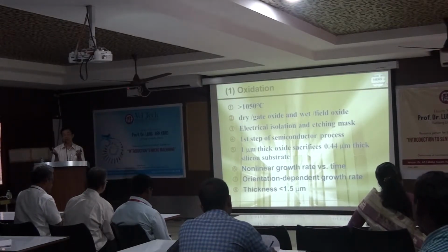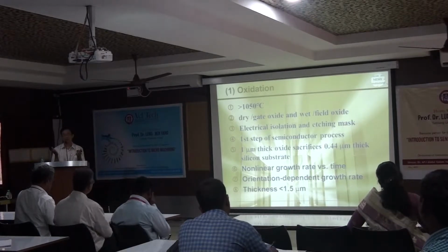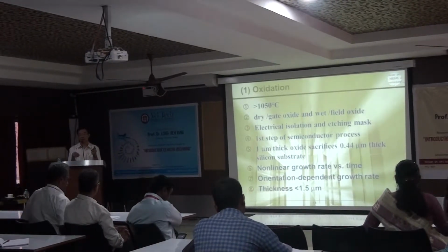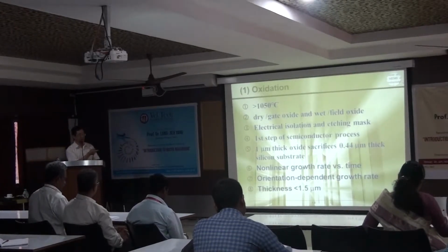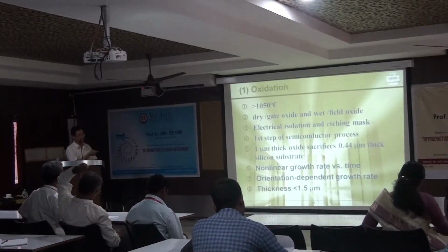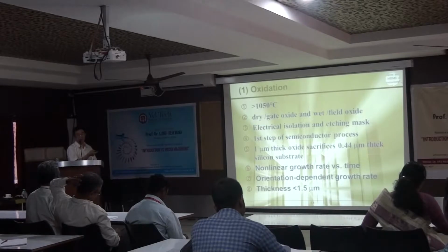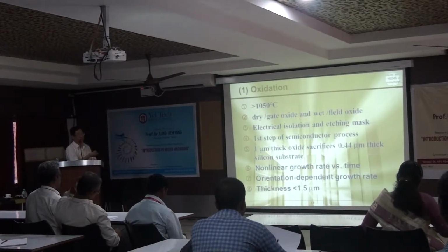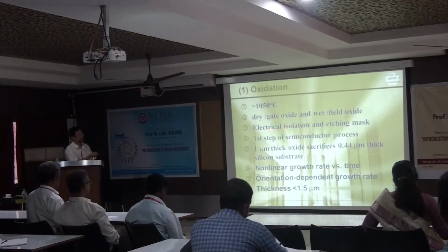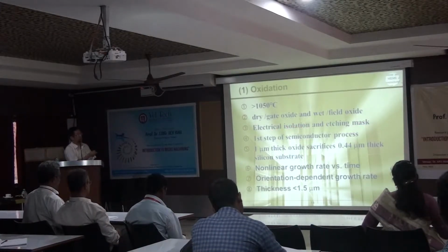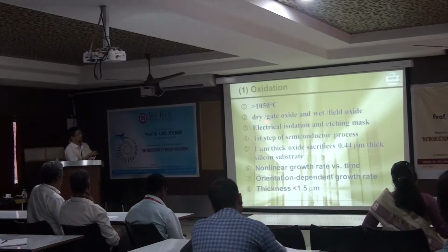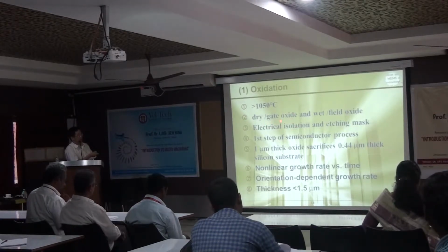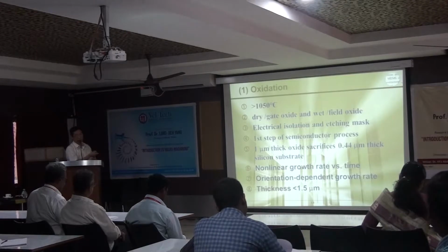Acid, even strong acid, we use the glass container to hold it. So it means that it can prevent the attack of the acid, strong acid. So it's good as an etch mask. So two functions for the oxide: electrical isolation and the etch mask. And also we have two kinds of oxide available for dealing with these two problems.